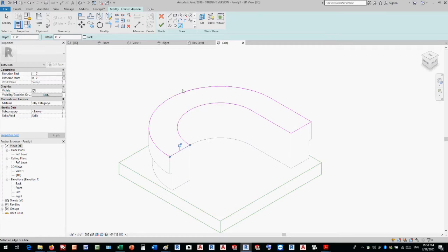And I'm going to use my offset tool by 3 inches. Okay, and I've got to make sure I turn off my copy option. And I'm only going to do this line, offset this one. That's all offset, offset, and offset this one. The inside is not going to be offset.